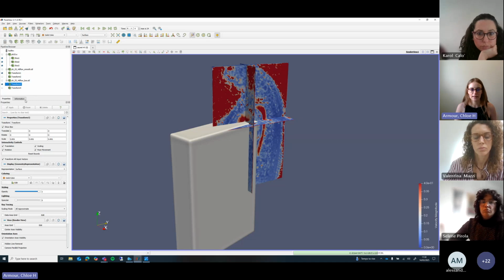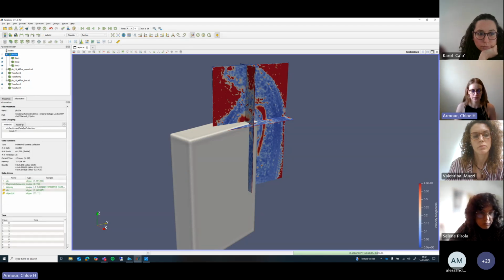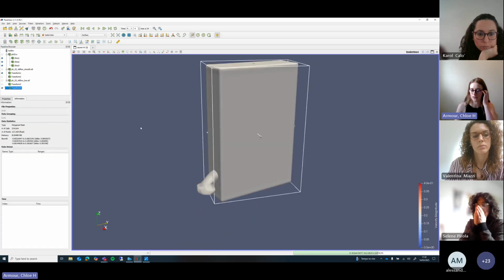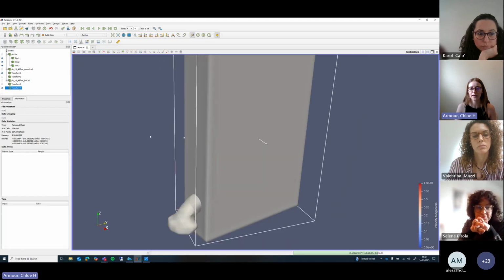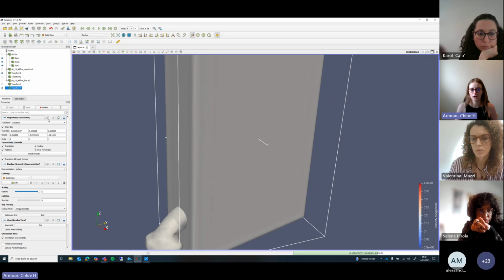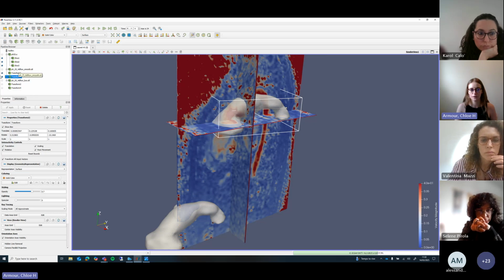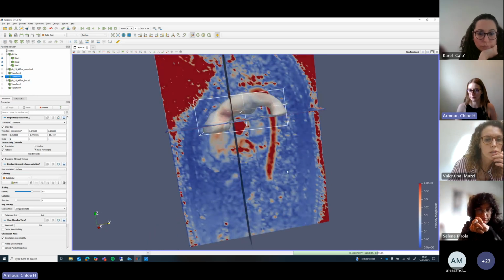With any item you have open in ParaView, you can look at the information and look at the bounds. This will work if, as I say, it's from the same machine at the same time of the same patient. You can look at the bounds of the one you're trying to register to, and then you can perform an exact transformation to set them up in line. When you perform any transformation, so I've specified a specific translation and rotation to match this, you can then copy these properties and apply them to any other transform on a different component, and that will shift the artery to be in line.